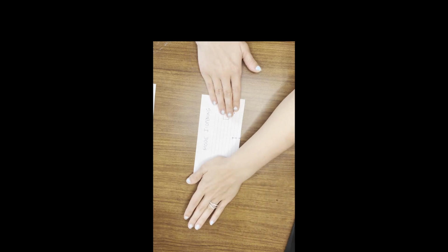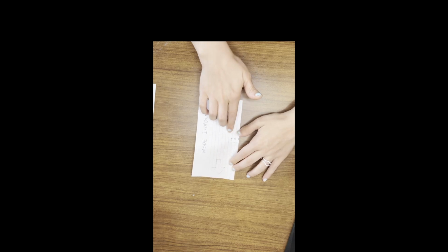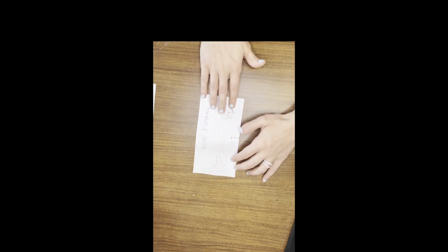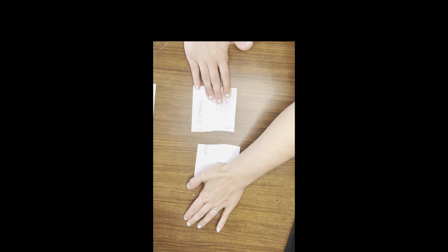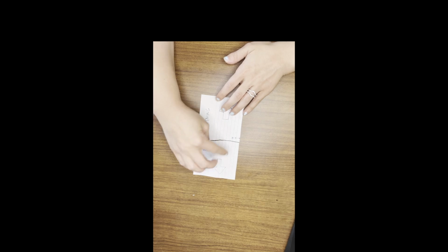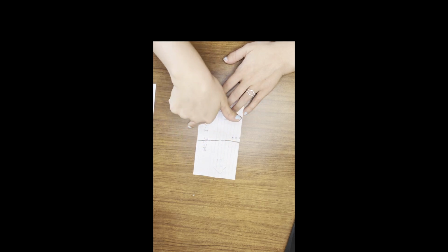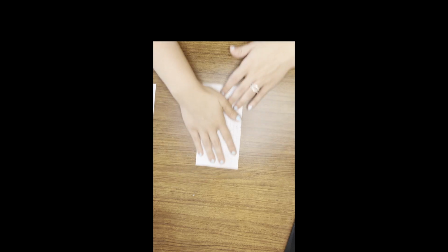All right, so I have set up here a demonstration for each of the 3 distinct crack propagation modes. So let's start off with mode 1. Mode 1 is the opening mode. This is the mode that we've already seen so far, and I have the arrows pointing in the direction of the load for mode 1. So this is crack opening. I've introduced a small crack here on the edge that's size A. And if I apply enough of a tensile stress, then a crack will propagate from this corner through my cross section. That's mode 1.